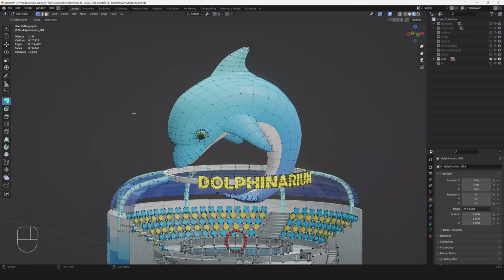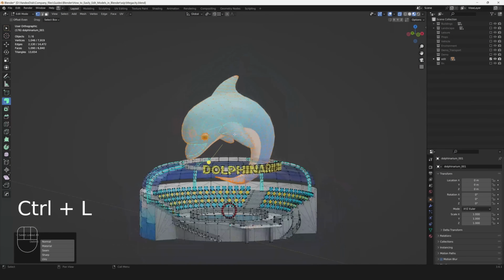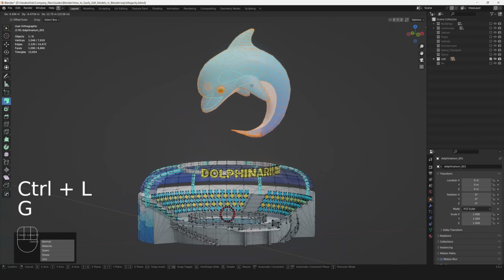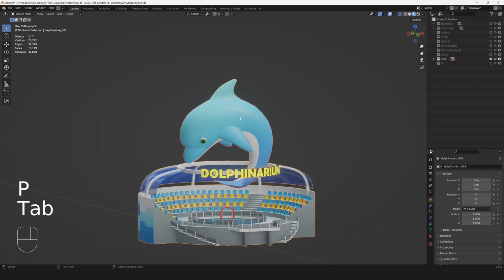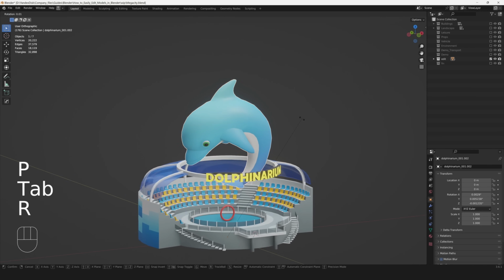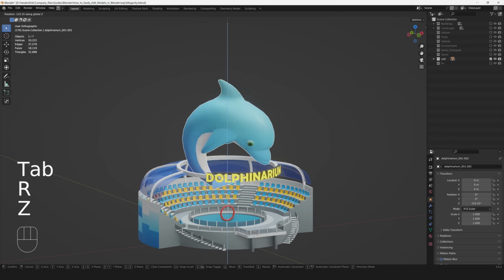So you can select your front surface vertices and also back surface and anything that is behind. Personally, I use this mode a lot because it's really useful. You can check if you selected everything you need by just dragging this object to another place. Now I should just again separate my geometry to another object.